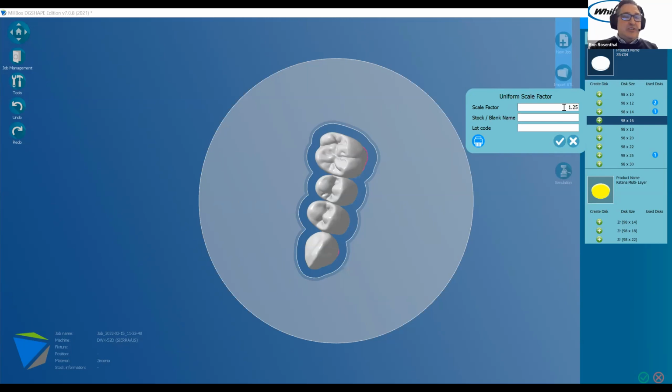And it is their shrinkage rate, because as we all know in the industry, zirconia shrinks 25% by mass. So usually the shrinkage factor or scale factor is on the side of your puck. In MillBox, if you don't have a shrinkage factor or you're moving fast and you don't want to put it in, you can leave it as the actual average that's there, 1.25, and it will shrink correctly and function correctly.